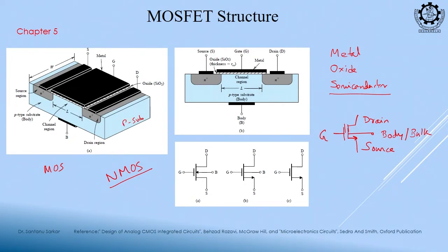First you have a silicon area, you dope it, make it P type, then on a selected area you make it N type. So, this N is your source and this N is your drain. Generally, apart from BJT, in MOSFET, source and drain are symmetrical, their doping and structure are symmetrical, so they can interchange.